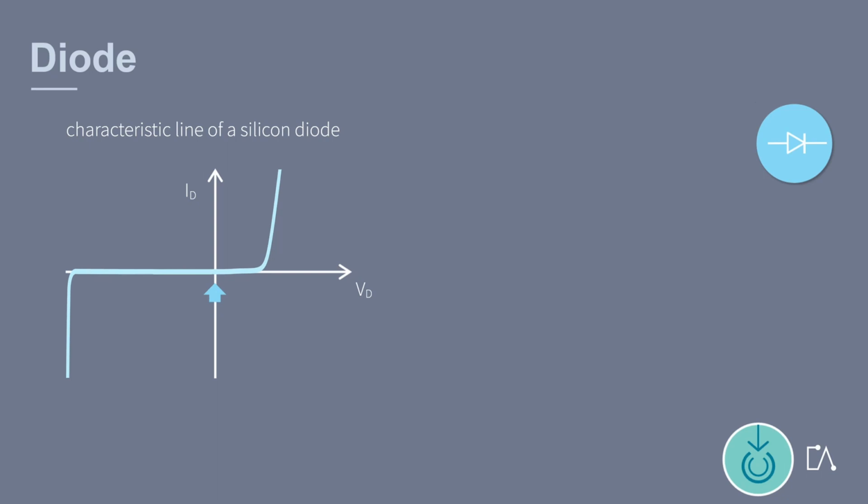At 0 volt no current flows through the diode. If we increase the voltage a little bit, still no current flows, because the depletion zone is not closed yet. For a silicon diode we need at least 0.7 volt. When we increase the voltage further the current rises rapidly. Therefore we have to be very careful, not to damage the circuit.